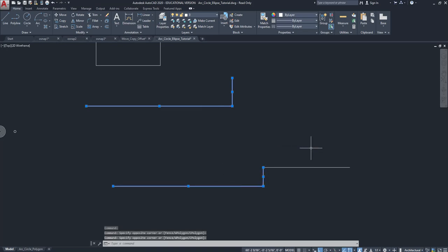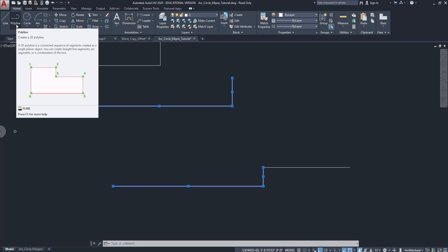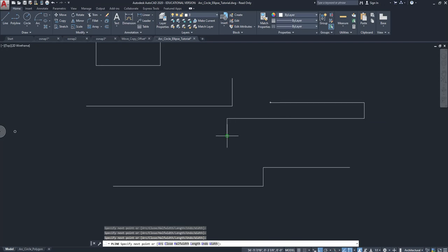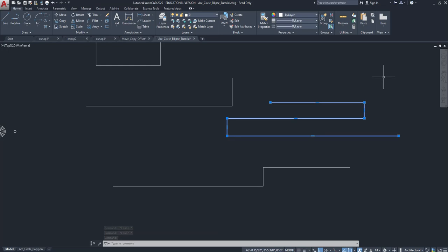All right. A polyline, okay, is this command right here. The shortcut is PL at the command line. And a polyline, click. When I create a polyline, it functions identically to a regular line. But when I hit escape and I'm done drawing it, when I click on it, it's all one piece, right? So this is kind of that same thing where we have a rectangle that is a polygon, or we have a rectangle that's 4 lines, right? Do we want all those lines glued together for easy manipulation, or do we want them all separate, okay?